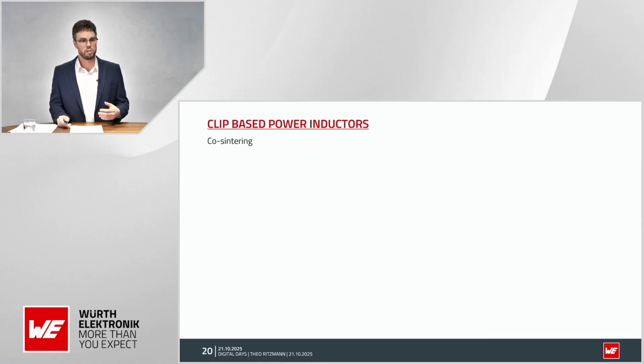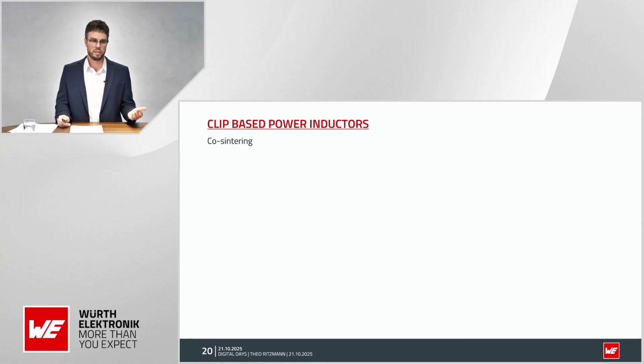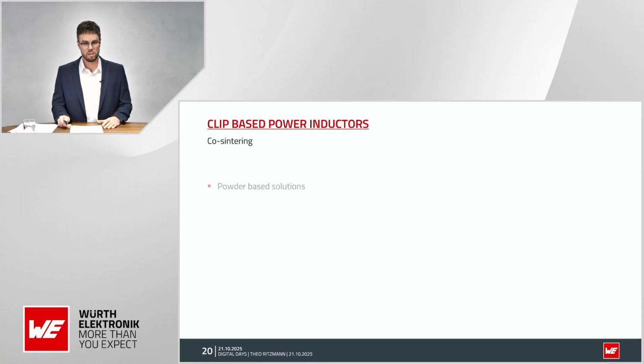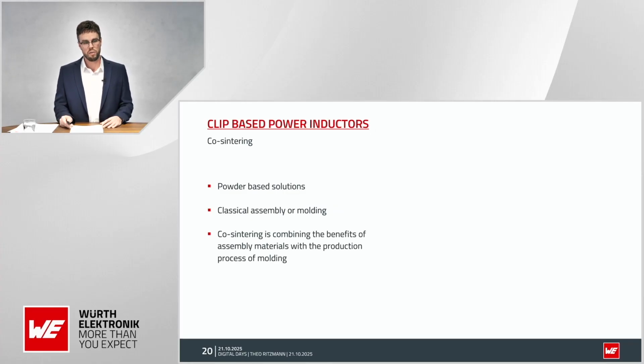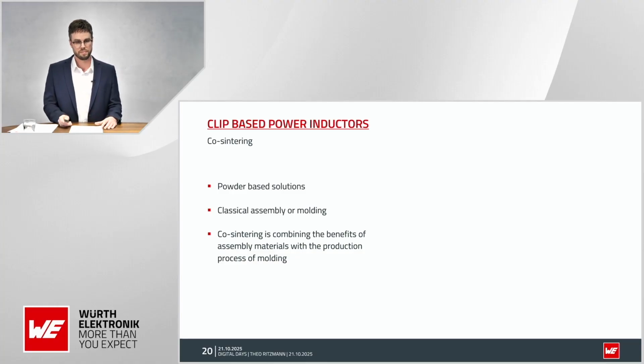But what's actually new now in the direction of the clip inductors next to TLVR topology? As said, the trend is going from ferrite into the powder solutions. For powder, we can either do the classical assembly or we can go for the molding process. But now there is a new technology called co-sintering, which is more or less the combination of both. So you can use the materials of the assembly process, but in the form of a powder to actually make a molding process.